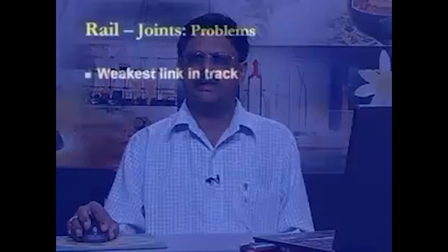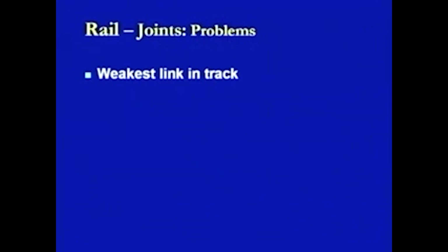Now, coming to these rails and their joints, we have of course discussed a number of factors which are the problems caused at any of the rail joints. We will be trying to look back again on all those factors which we have discussed previously under different lectures. What we have found is that the joints are the weakest link in a track. This is a point of discontinuity, and because of this discontinuity and the gap being provided between the two sturdy rail sections, whatever load is coming at this point is unsupported in nature, and that is why this is one of the weakest links in any track.